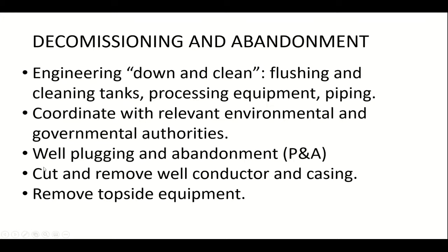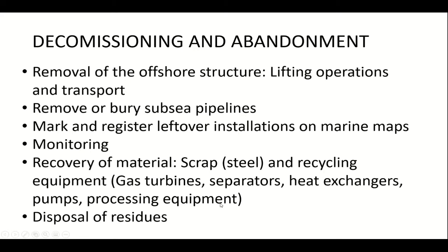This usually involves cutting and removing the well conductor and casing. Then the topside equipment has to be removed. The offshore structure usually has to be removed, and this requires lifting operations with cranes, with vessels that come and take part of the structure and transport it to shore. Sometimes it can be allowed to leave subsea pipelines but bury them, such that they don't cause issues with, for example, fishing. That's also something very important.